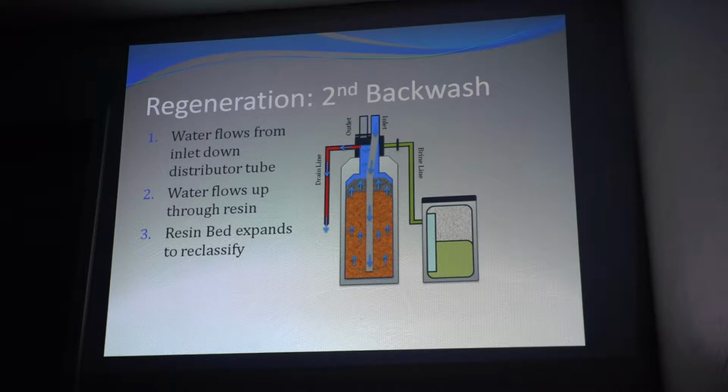They can go directly to where they want to go, rather than going all the way around. They can move multiple directions by switching polarity. AC is alternating current, so you can't switch polarity. It doesn't matter which way you wire it. With DC, you have a positive and a negative. If you switch polarity through the controller to the motor, it'll reverse.